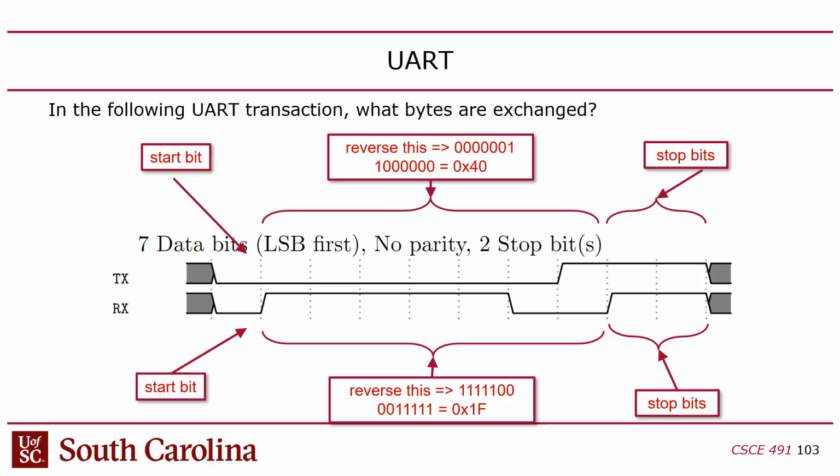And so now I'm trying to read the bits sent on UART. I have it shown here as least significant bit first. Is that generally how it's sent, or is that an optional thing? I think you can switch it, but I think it is generally least significant first. Yeah, I think that's how I remember it too.